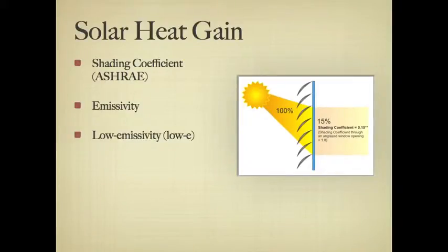In the 1960s, the American Society of Heating, Refrigerating, and Air Conditioning Engineers established a procedure for estimating the solar heat gain of a window system. The total shading coefficient is a measure of the total amount of heat passing through the glazing compared with that through a single clear glass. The shading coefficient is derived by comparing the solar radiant heat transmission properties of any glass with a clear float glass having a total heat transmission of 0.87.